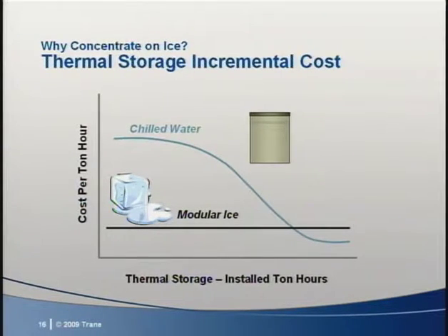There are two distinct advantages that chilled water storage has versus other technologies. One, that it can be very rapidly discharged. It takes a few hours to discharge an ice system, while a chilled water system can be discharged as fast as you can pump the tank. Secondly, in the case of an emergency, the stored water can be used for other purposes, such as fire suppression or as cooling tower makeup water. Insurance companies may give rate discounts for such secondary uses.